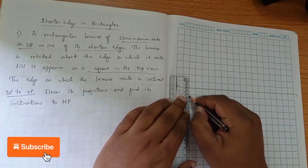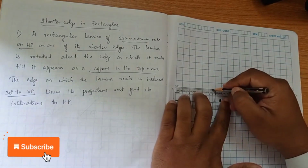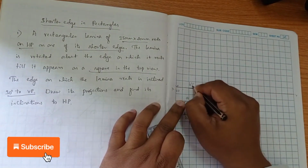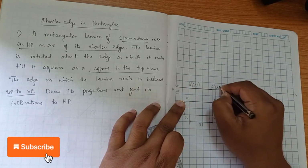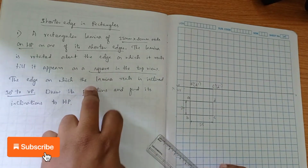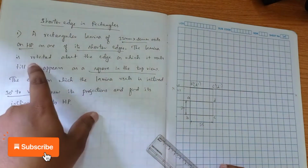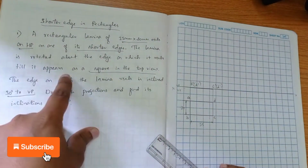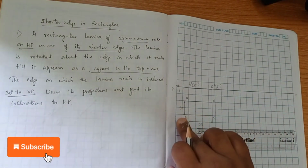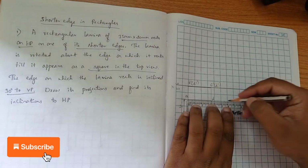So we'll draw the front view. Okay, so B dash and C dash are visible, but A dash and D dash are not visible. So you can see in this problem they have not mentioned the second position. Instead of that they have mentioned that we get a square in the top view, that the lamina is rotated about the edge on which it rests till it appears as a square in the top view. So if we project it here, we get a square of dimension 20 here.